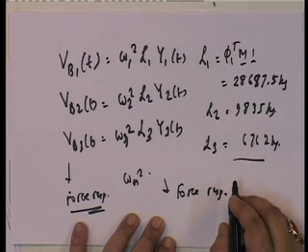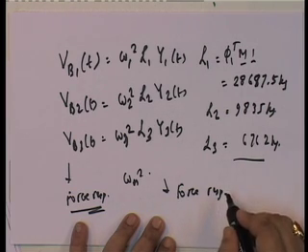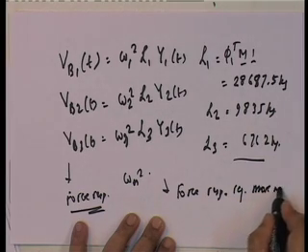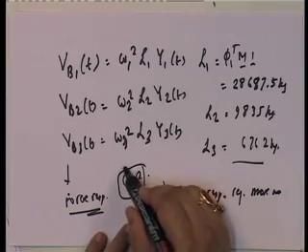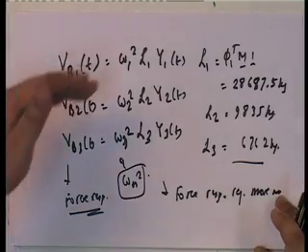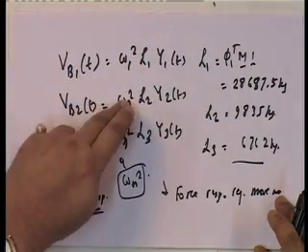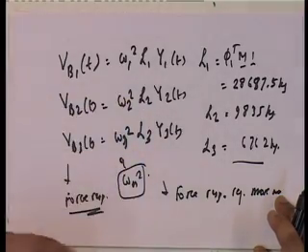So, the force response requires more modes because they are multiplied with omega_n squared. As omega_n is being multiplied, the contribution of the higher modes to force responses is more than to displacement responses. This is another very, very important aspect that you need to consider.